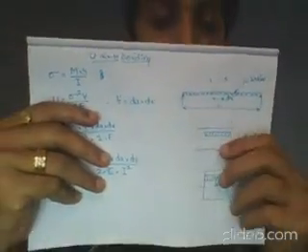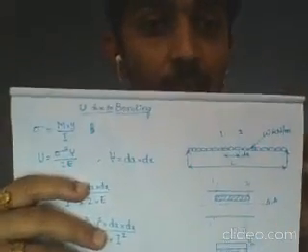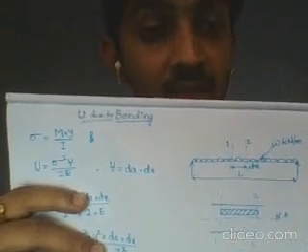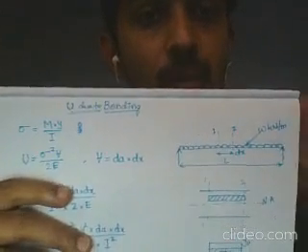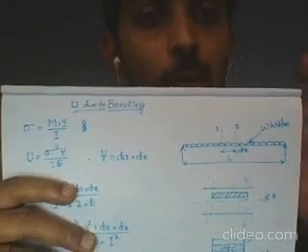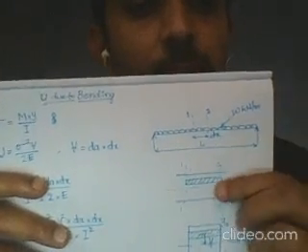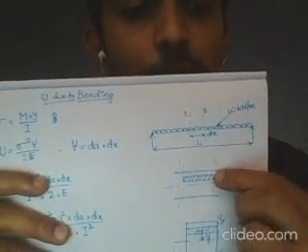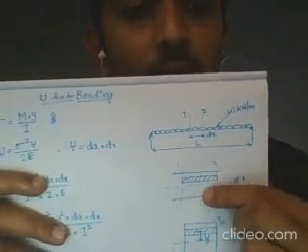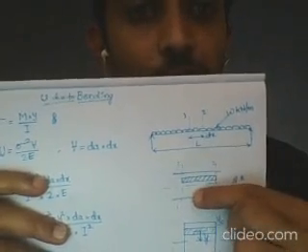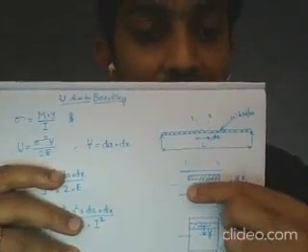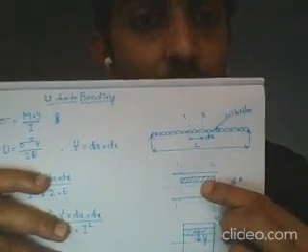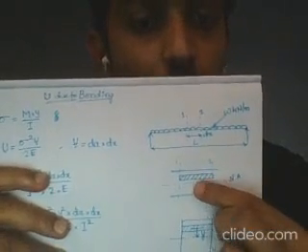It is just like the experiment we have done, the Wagner beam, where some of the strain gauges we used undergo compression and some undergo tension. Similarly, when the load is applied from the top, above the neutral axis it is going to be compression, and below the neutral axis it is going to be tension. That will lead to deformation at the elemental level. So it is not deflection anymore, it is deformation.